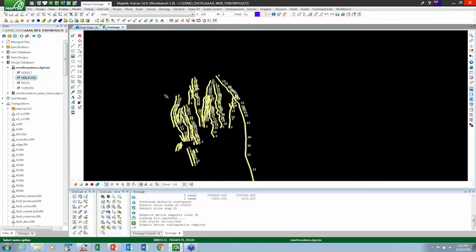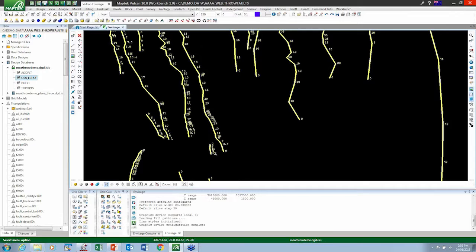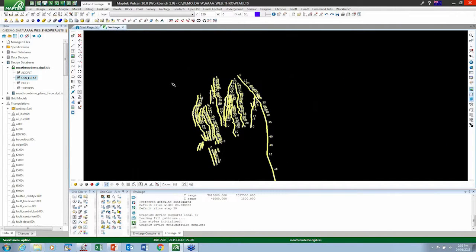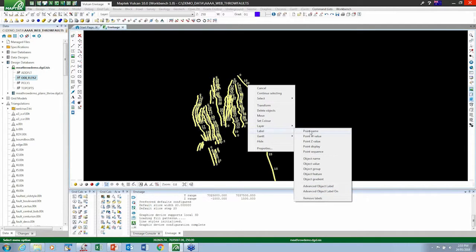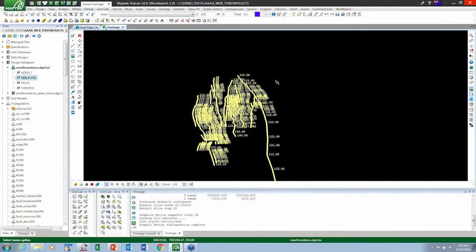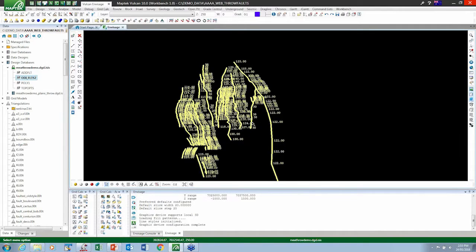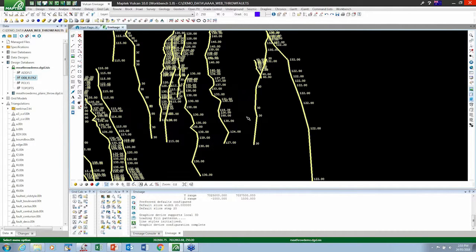But if you imagine looking at this and saying, okay, how am I going to break these up into individual solid domains? Especially with these sort of sub-parallel fault layouts, it's quite difficult, or little faults like this thing here. So rather than have to do that, we introduce a new method which allows you to have the throw encoded in each of the strings, but also the dip. So the dip itself is encoded in the point name. And you can now see each of the points can have its own varying dip.